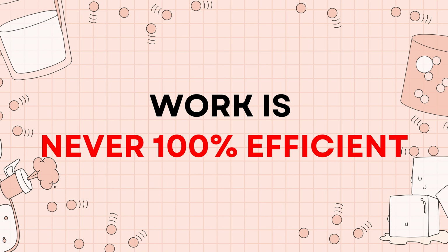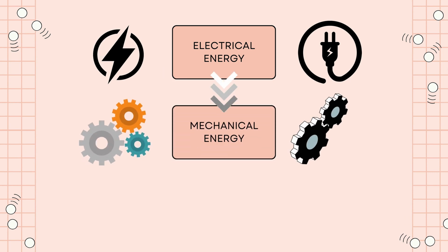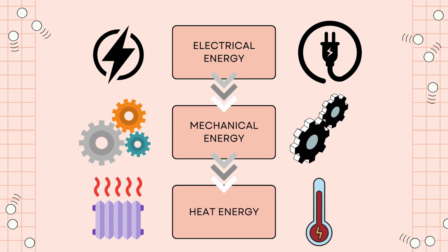Another implication of the laws of thermodynamics is that work is never 100% efficient, so there will always be some amount of energy that is used but does not contribute to the work's results. Normally, this energy escapes the system as heat. In this case, the energy being used to do the work is electricity, which is transformed into mechanical energy in the motor that drives the pump that keeps the refrigerant moving through the cycle that moves the heat. A small amount of that electrical energy becomes heat due to friction in the motor, and that heat makes its way into the system's environment.